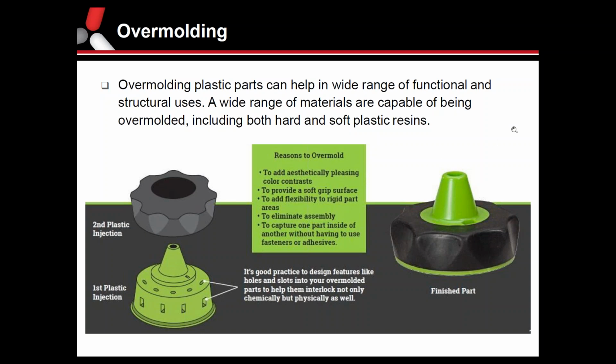Always a good idea to get the material representatives involved. Certain materials don't bond well to other plastics, so it's always a good idea to get your design in front of a plastics supplier to make sure that we're using the proper resins to bond to the substrates.